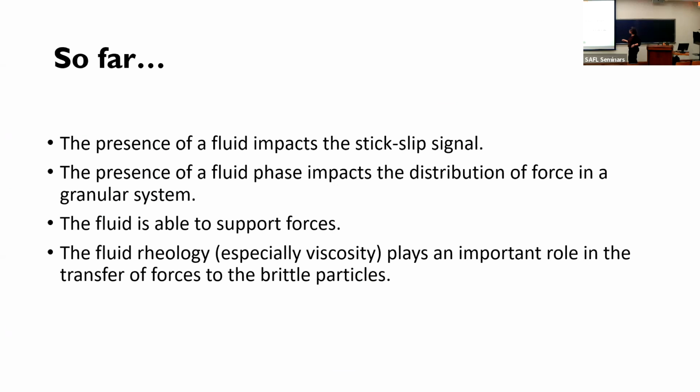So far, we've hopefully seen that the presence of the fluid has an impact on the stick-slip signal, and that if we have a fluid present, we're going to change the distribution of the forces in our system, and the fluid is able to support part of this force over at least a limited amount of time. We also saw that the exact rheology of the fluid seems to not play that big of an impact as long as the viscosity is high enough. So we can transfer the stresses from the fluid onto the solid.